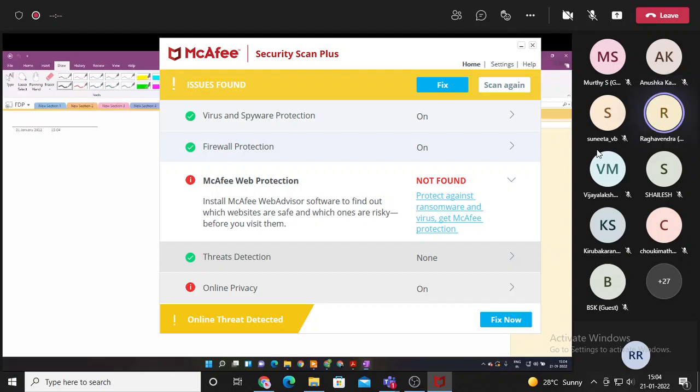The problem arises when we have to actually transmit and receive using visible light. So the front end for that is something that we developed on our own. The concept is pretty simple. For a transmitter, we have two small PCBs, where the first PCB takes in the input from the USRP using an SMA port, similar to what you would connect an antenna to. It's exactly the same. In this, what happens is, this power is connected to an SMPS.